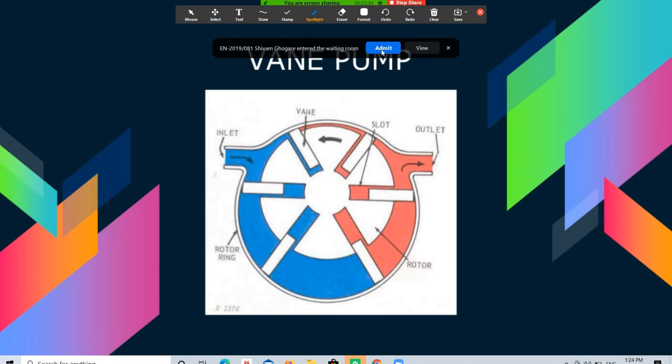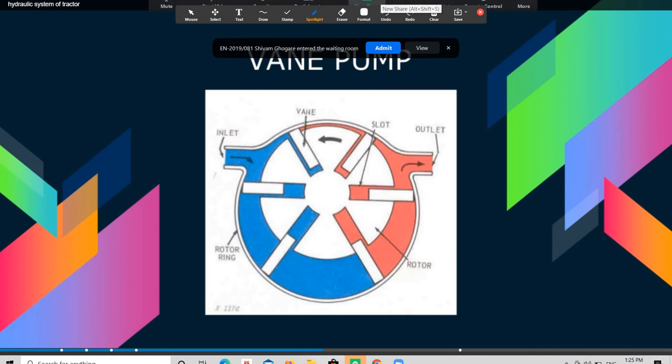and it usually withstands a little more pressure, delivers a little higher efficiency, and costs a little more, and it has good contamination resistance when new, because the contaminated fluid is easily swept from the inlet to the outlet, and wear of the vane tips can be accommodated by further extension. When the vane is fully extended, any further wear can result in a catastrophic failure of the pump as the vane slips out of the rotor.